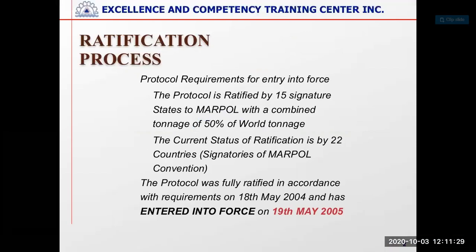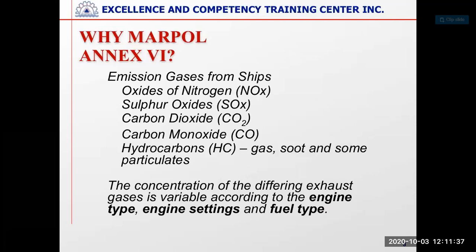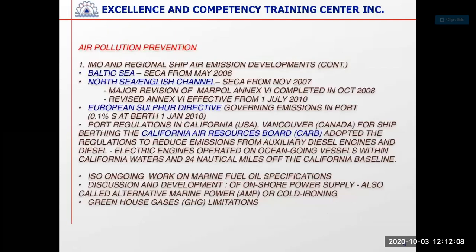And all MARPOL annexes have a ratification process, and after that it entered into force on 19th May 2005. It's the latest. So what are the gases which are responsible for air pollution and related to MARPOL Annex 6? Oxides of nitrogen, NOx, sulfur oxides, SOx, carbon dioxide, CO2, carbon monoxide, CO, hydrocarbons, soot, and some particulates. The concentration of different exhaust gases is variable according to engine type, engine settings, and fuel types. So as per the engine RPM and the type of engine, we will see different requirements.